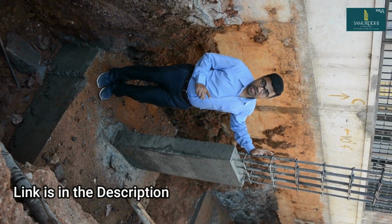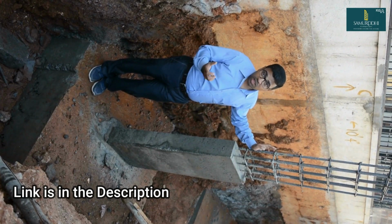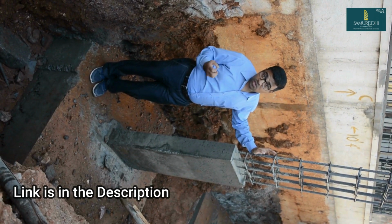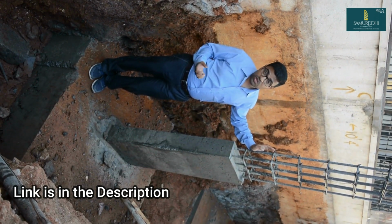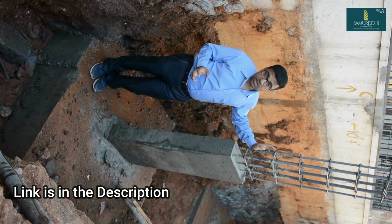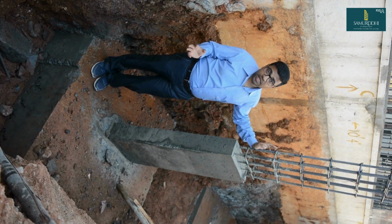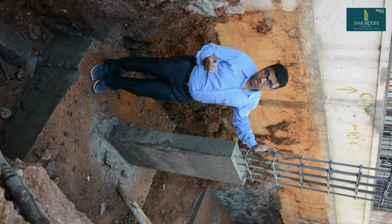In those circumstances, the foundation which is designed will not have the capacity to hold the strength, and the soil collapses. At the same time, the foundation also collapses, thereby the entire structure comes down or falls down. So it is so important that we do the soil testing at our place to know the strength of the soil and then design the structure accordingly, so that the stability of the structure is always at the maximum.